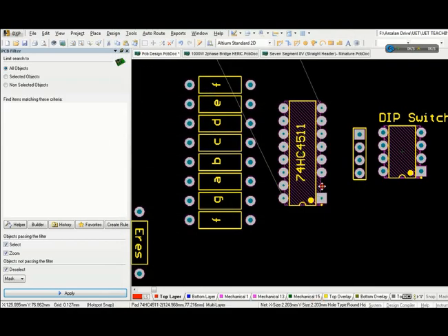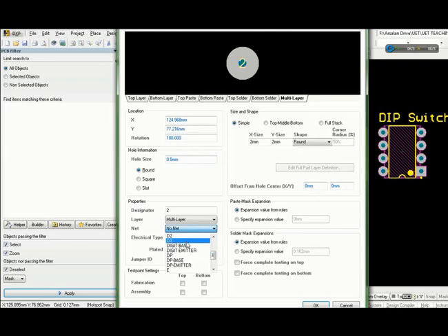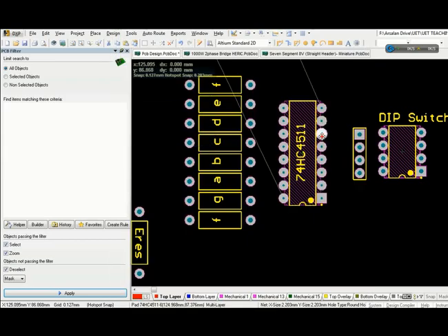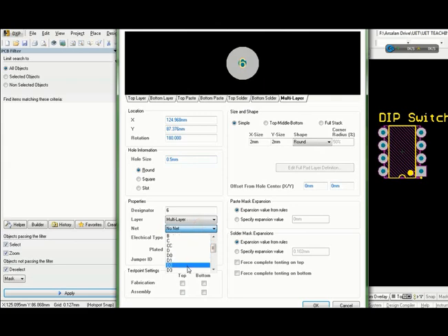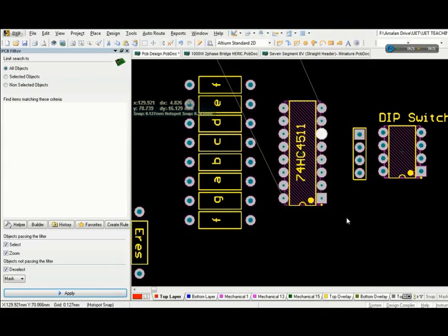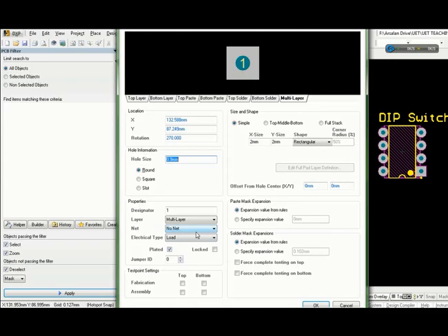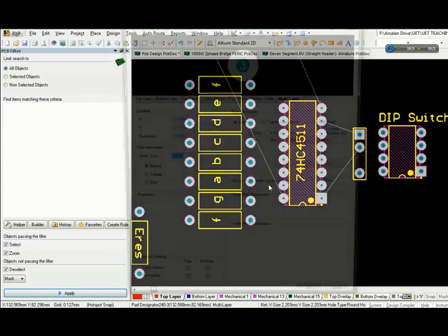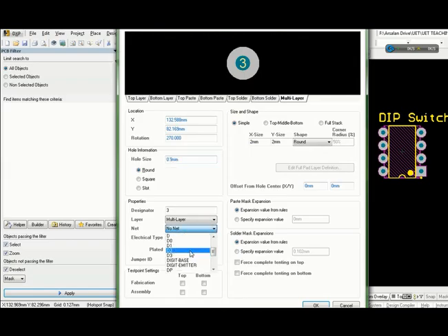So you can see now I am pointing D0, D1, D2 and D3. Certainly, I remember the datasheet, so that's why I am not opening that datasheet every time. But since you are just going to be newbies, you should check it. Don't forget to select pin number 3 and pin number 4 as 5 volt and pin number 5 as ground. That is a must over there.